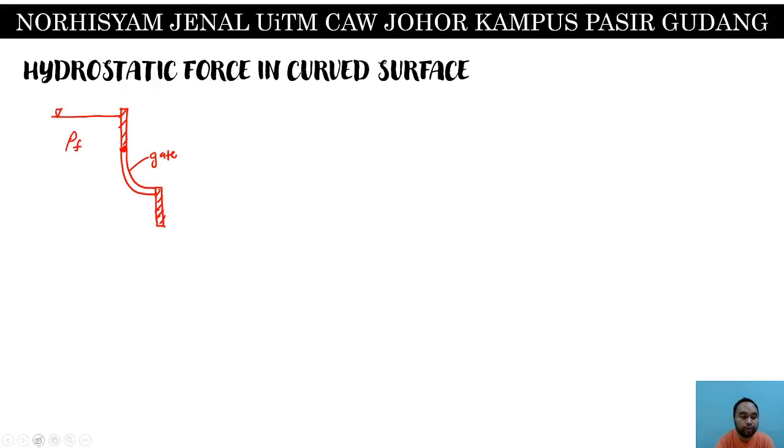and this is the fluid rho F. Okay, so if you need to draw the volume, instead of a quarter circle, the volume for this particular picture, if you draw the vertical line or vertical representation and the horizontal line, you will see that the volume will look like this. Okay, so the volume is different than the volume that we have before, but we can still put Fr, Fv, Fh, W will be downward, Fx and Fy. So remember, your F should be acting towards the volume and the W should be acting downward because we are following the gravitational effect.